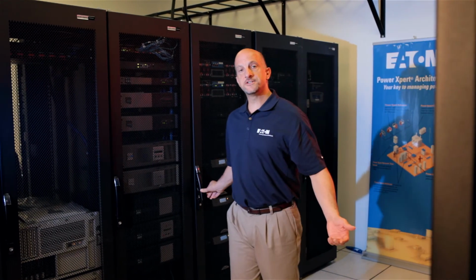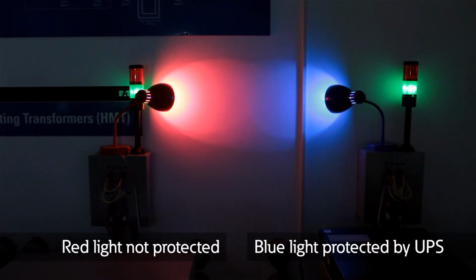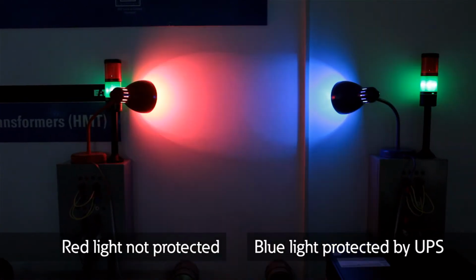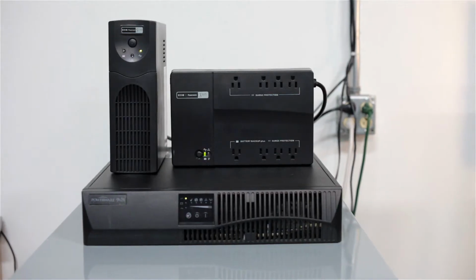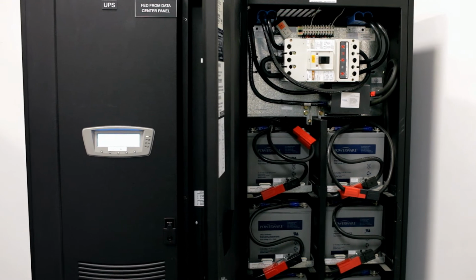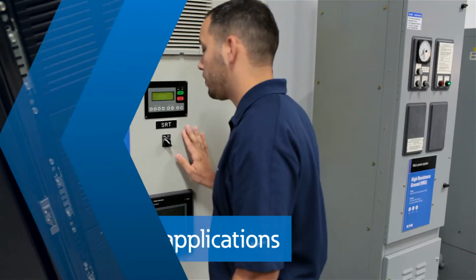The cost of voltage sag protection depends upon the equipment size, the tolerance, and criticality of the loads. The protective equipment can range from small single-phase UPSs to large multi-megawatt facility solutions. Watch the difference between these two lights during a voltage sag event. The blue one is protected by a small double conversion UPS while the red one is not. There's a large range in the types and sizes of UPSs that vary substantially in cost and in the different power quality problems they can correct.